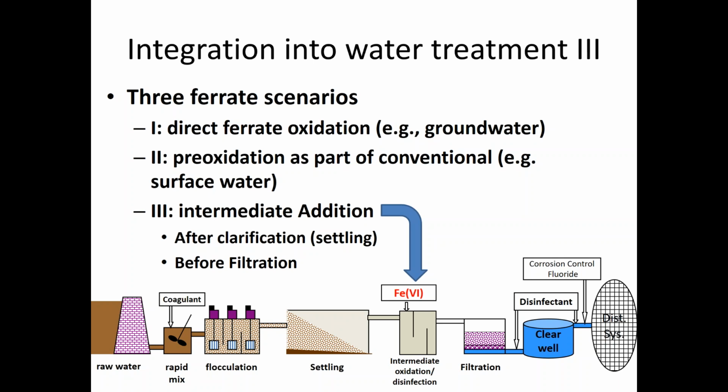And we've been looking at this also in laboratory scale and continuous flow pilot. And what we see is much like what we see with ozone, in that it doesn't seem to create any additional head loss buildup. It doesn't cause a deterioration in granular media filtration in any way, even though you are producing some solids. Interestingly, the solids aren't of the type that caused the filter head loss buildup.